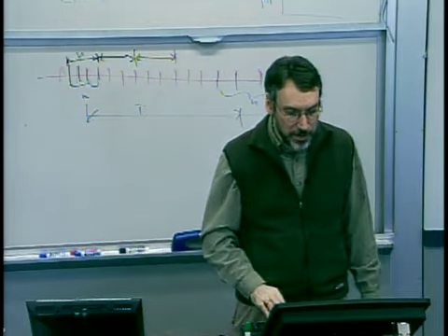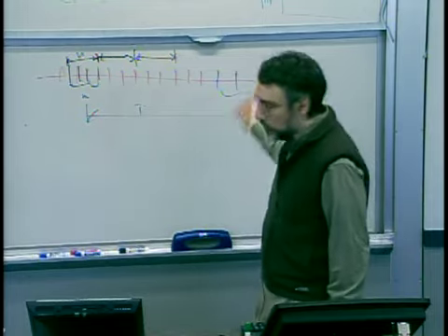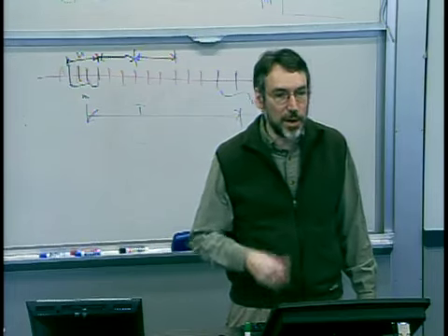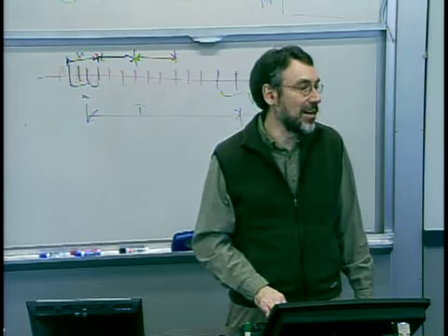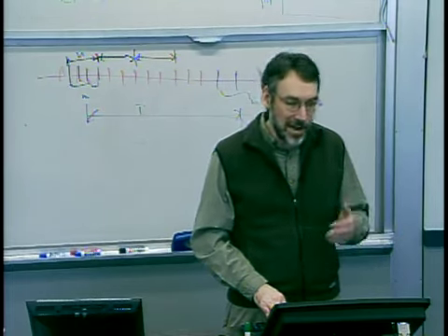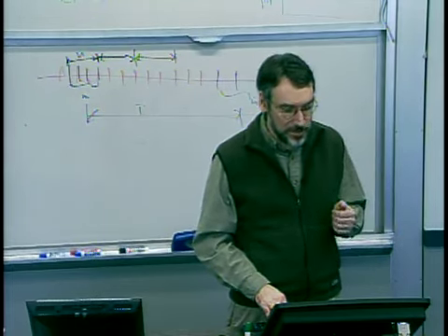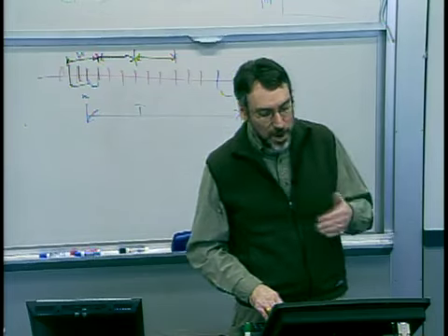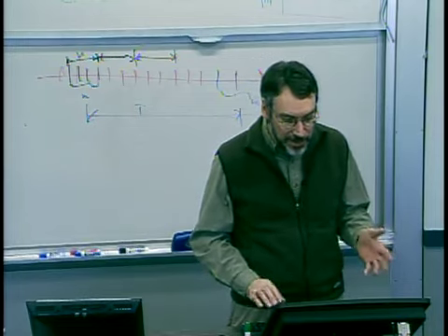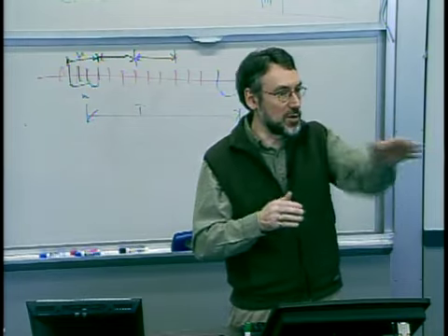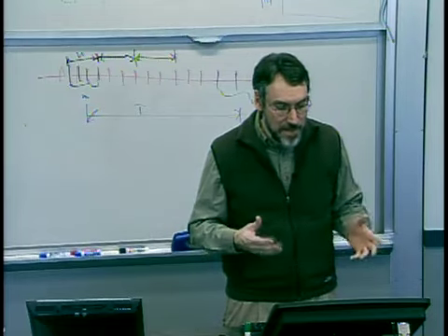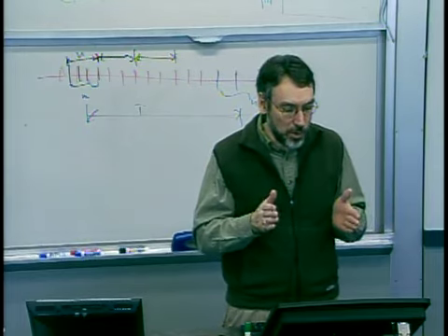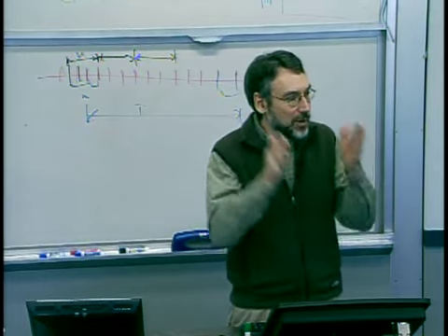You could also have the desire to not have too many false alarms, so you still want noise rejection. And one of the problems with some of these is you might, in fact, have higher variance estimators, and you've got to be very careful because you can get larger false alarm rates unless you compensate for that. But the basic idea, and this almost goes back to your earlier question, imagine first off what we're doing with just a regular X-bar chart, but where we're measuring every part and then just aggregating in samples of different size.